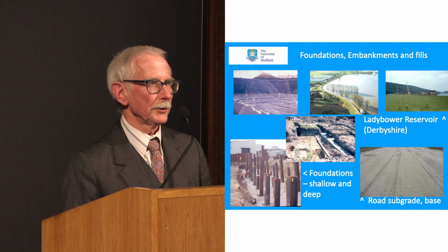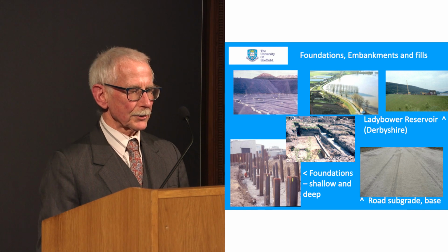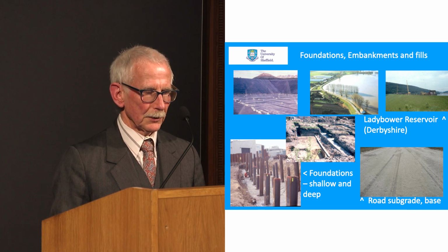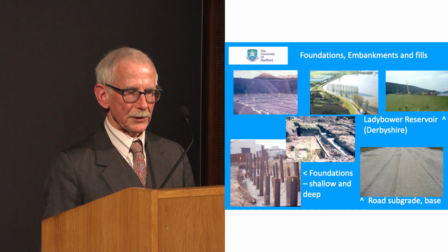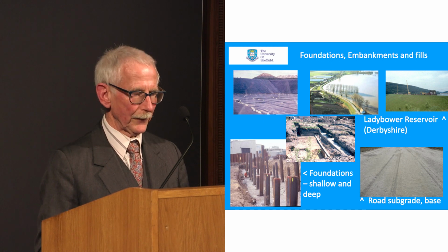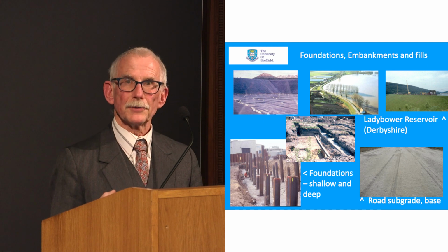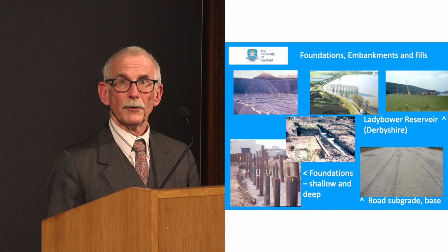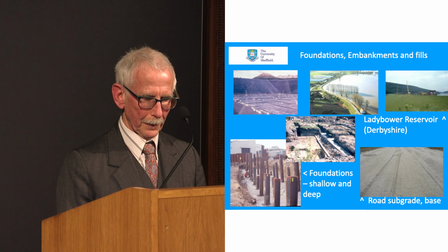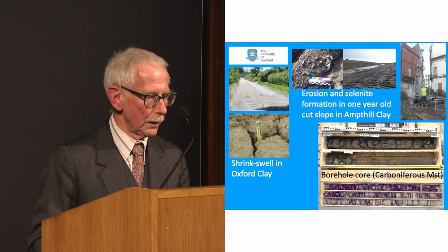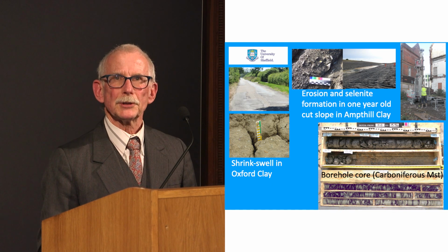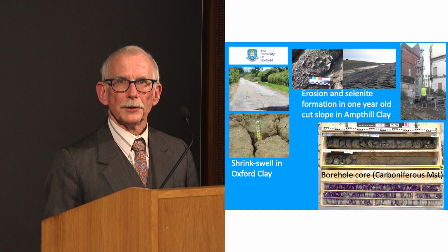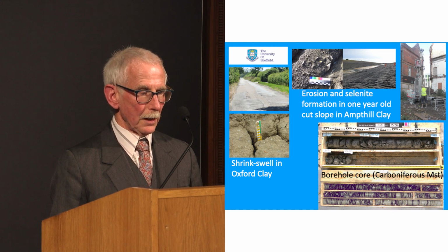Sometimes mud rocks are used as the construction material, such as in embankments, dams, landfill cells, and infrastructure projects, and they serve as the in situ material for shallow and deep foundations. It's necessary to know their geotechnical properties and their performance as fills. Some types of mud rocks are prone to shrink swell behaviour, such as we see in the Oxford clay on the right-hand side of the slide.